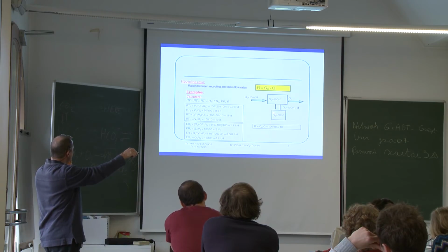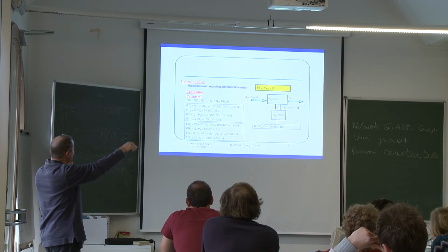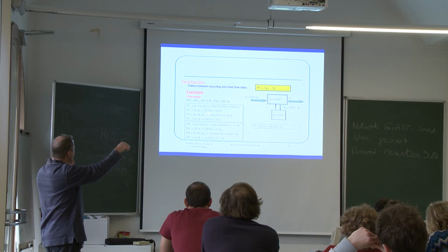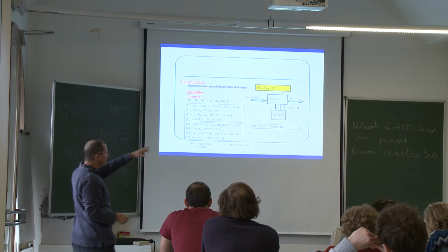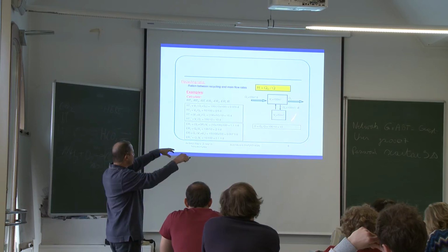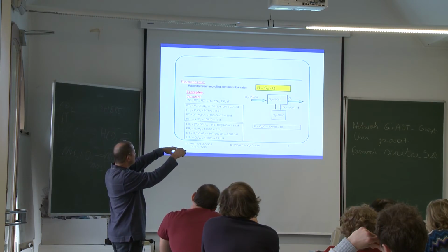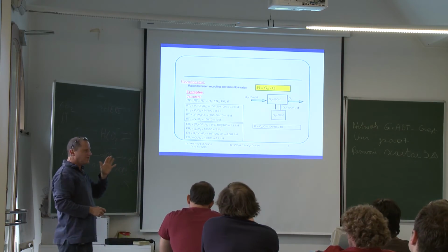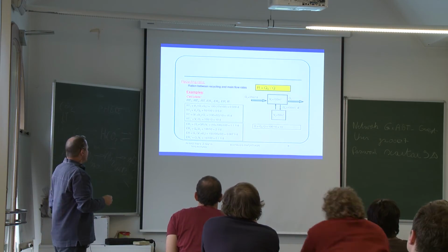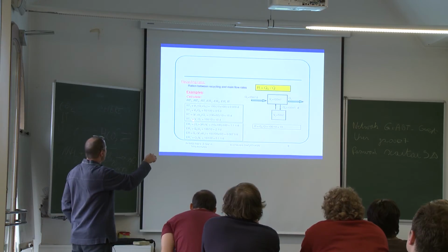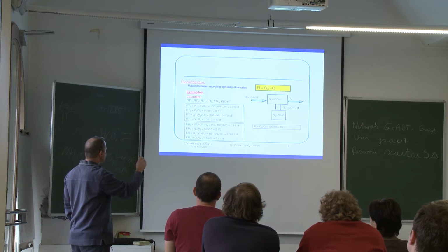And the retention time here would be just the volume over the Q that gets into this system, okay? So it'd be only half a day. And the overall retention time would be 15 days as we had before. You remember, because it's 150 cubic meters when you introduce 10 cubic meters a day. So overall, it'd be 15 days before we exchange the water. That's simple. And we can also talk about the retention time of only this tank.